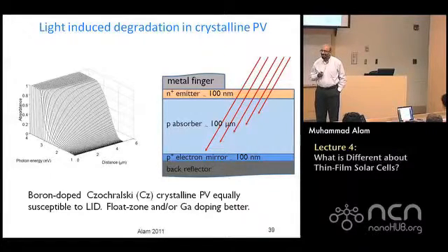So that diode factor, I'd assume between 1 and 2, and very robustly about 1.5. 1.5 to 1.8 in that. Yeah. So it's in between 1 and 2. Not perfect 1 and neither perfect 2. Especially for these structures. And you interpret that like recombination in a space charge region? That's what's giving you some.